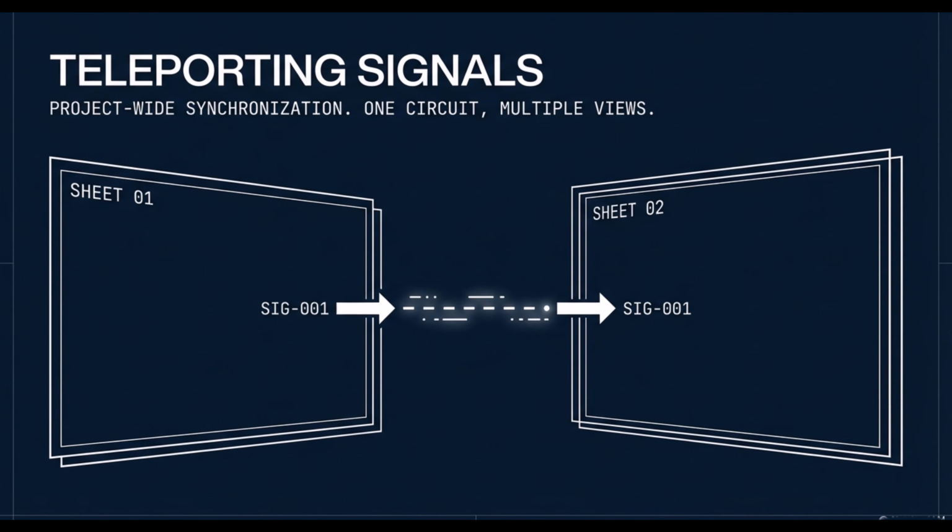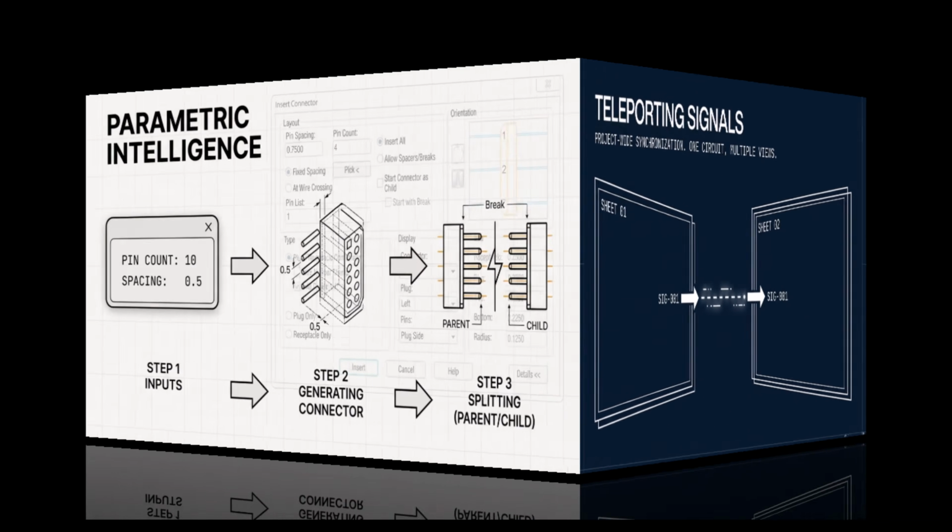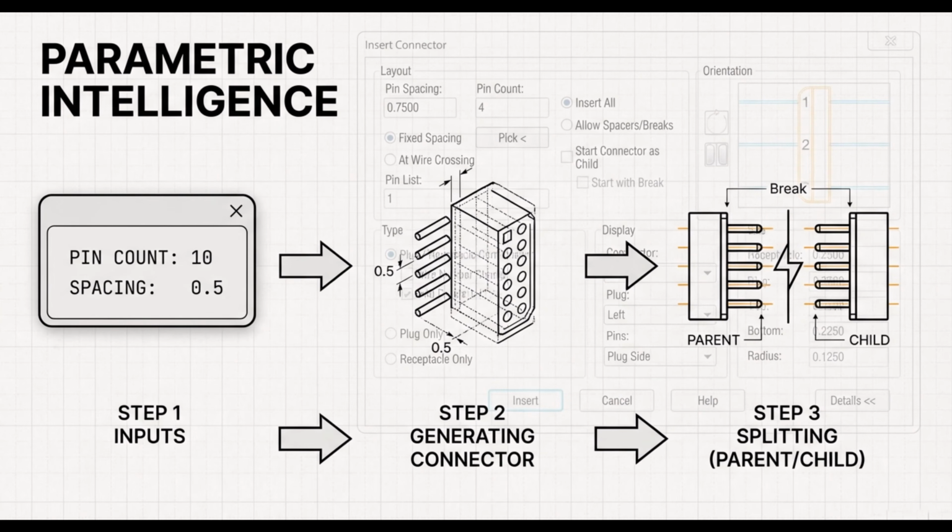And this is crucial. Set the wire numbering property for that layer to no. So it doesn't get a wire number tag. Exactly. It doesn't clutter your drawing. It doesn't clutter your BOM. It just silently bridges the logic so the database knows A connects to B. A phantom wire for the sake of the database. It's a perfect example of knowing how the software thinks, not just how it draws.